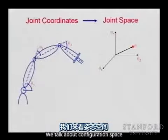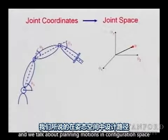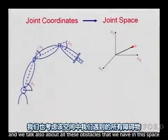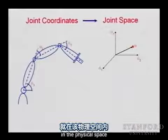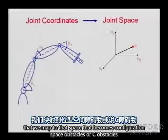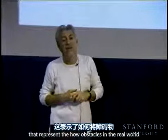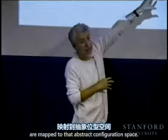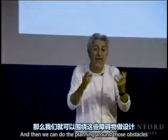We talk about configuration space, and we talk about planning motions in configuration space, so planning the motion of theta. And we talk also about all these obstacles that we have in the physical space, that we map to that space, that become configuration space obstacles or C obstacles, that represent how obstacles in the real world are mapped to that abstract configuration space. And then we can do the planning around those obstacles.